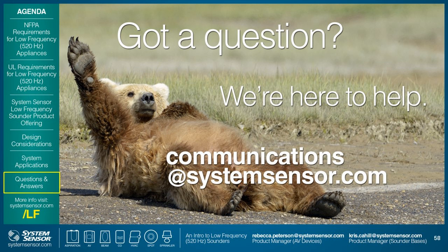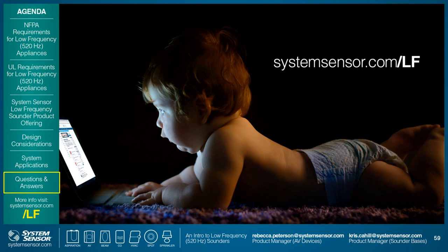They ask, what reporting or documentation do I need to produce so I can validate this UL listing? For the low-frequency sounders, as I mentioned before, I showed a snapshot of our listing card. So the listing of the devices is the verification that you would provide. Also, there's the marking on the housing, and on the nameplate, it'll say low-frequency appliance, something of that nature.